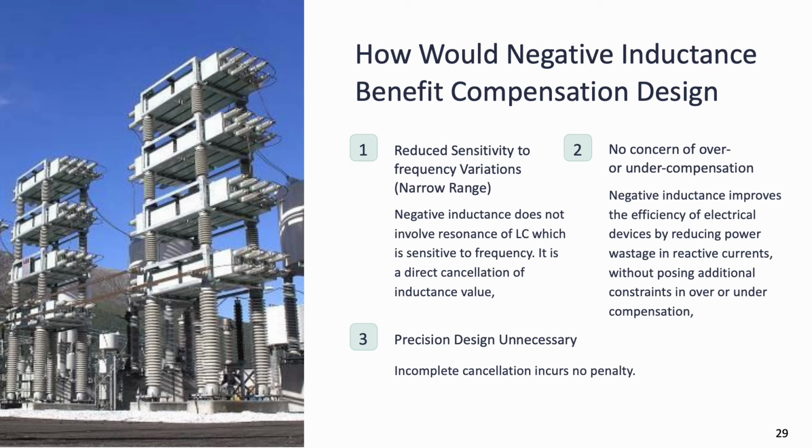And finally, precision design will be unnecessary. In fact, it's no longer crucial to have capacitor and inductor values to be designed precisely for self or mutual cancellation at specific frequency or a narrow range of frequency.